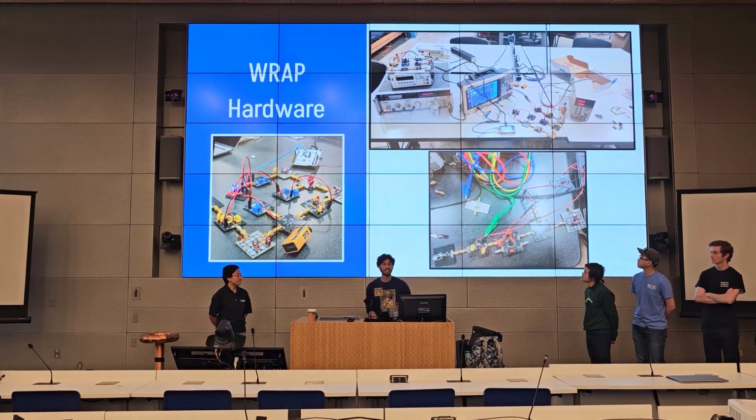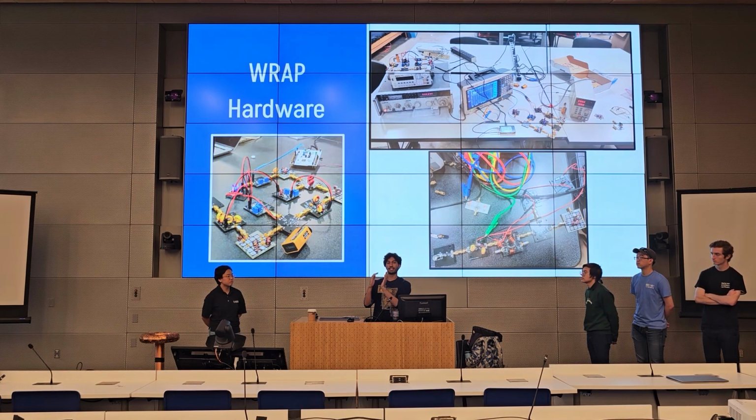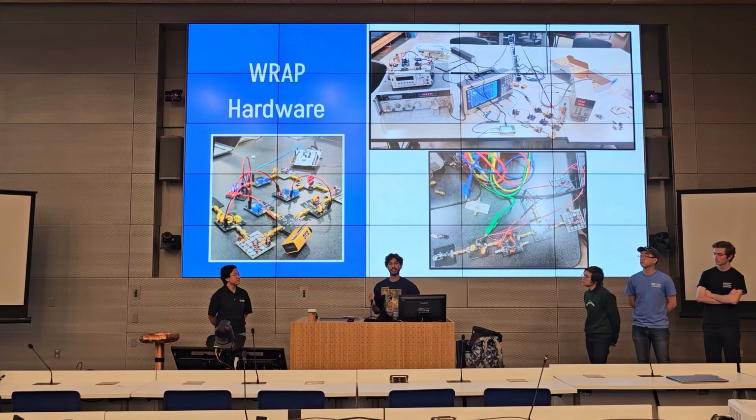And on the bottom here is something that I've been looking into as more of an R&D aspect of RF. It's a direct conversion system. What's happening in our basic system right now is we go from a 1 megahertz signal at our MCU, up converted to 27 megahertz, get transmitted, received at 27 megahertz, down converted back to 1 megahertz, and then sampled at twice that rate. So that's kind of cumbersome. It takes up a lot of processing speed, and it's not the most efficient way of doing so.